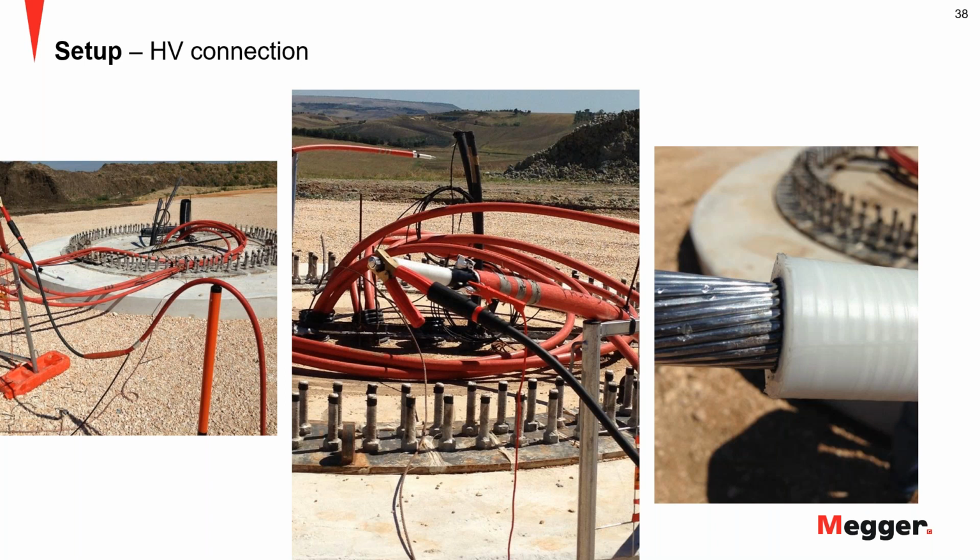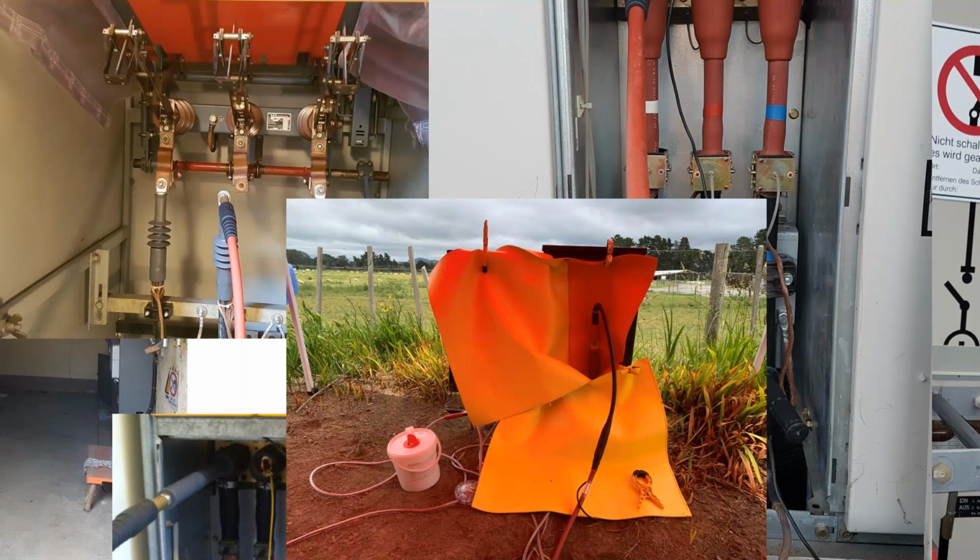Another pitfall would be, in this case it was kind of okay, but generally speaking, this type of trick in the field does not work very well. The main thing for you is clearance, clearance, clearance, clearance. If you don't have clearance and you can bend the other cables in a switchgear nearby, let's say you disconnected the cable from the switchgear, and you can bend it back and make room around there, that is far better than trying to put rubber boots or rubber blankets, because you will have surface discharges there.